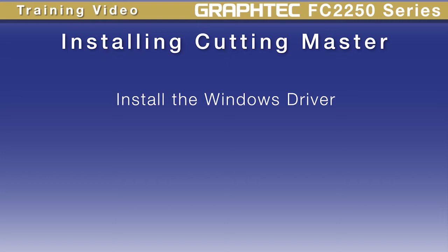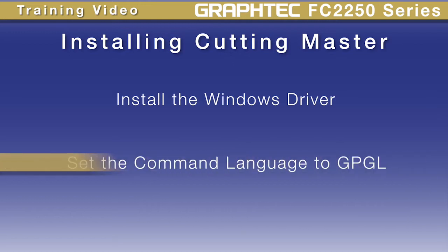Since Cutting Master 2 outputs to Graphtec's cutter language, known as GPGL, the cutter will need to be set to GPGL mode. This was covered earlier in this lesson. If you are not sure, review that portion of the lesson, or review the Cutting Master 2 manual. Finally, prior to installing Cutting Master 2, remove any previous versions of Cutting Master 2.